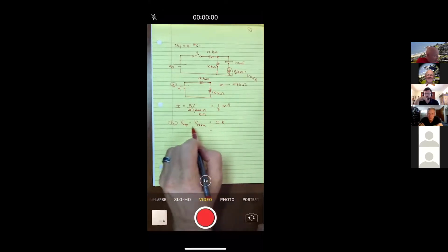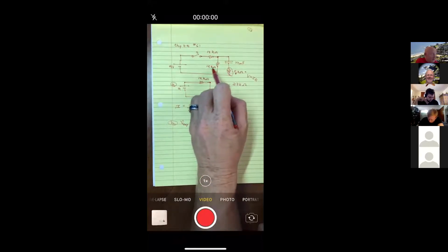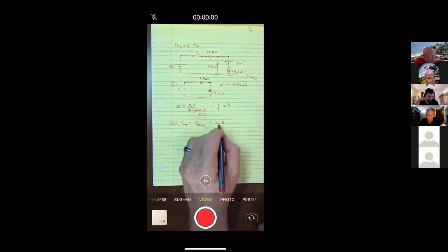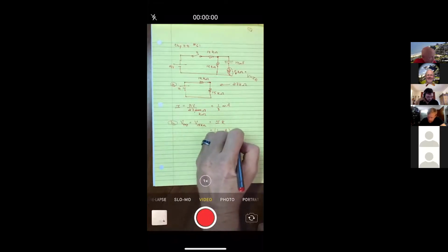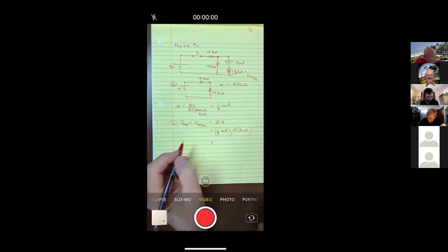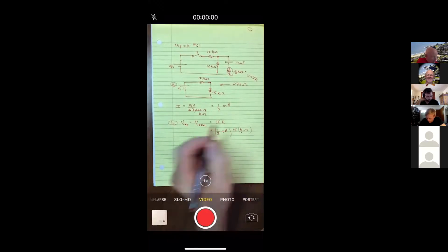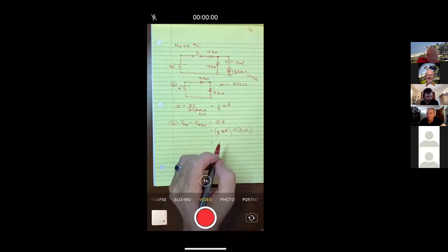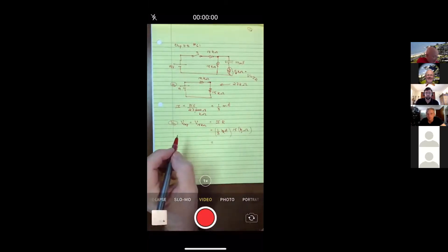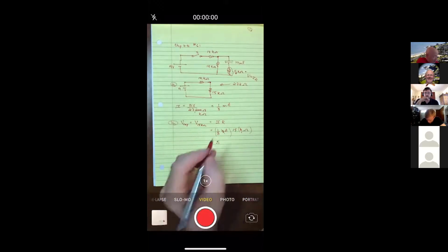So I'm going to be able to figure out what the voltage is on the capacitor by realizing that it's the same as the voltage on this 15 kilo ohm resistor. So the current we just did a moment ago as 1/3 of a milliamp, and the resistance is 15 kilo ohms. And again, maybe another little mathematics here. A milli times a kilo would cancel, right? So this is 1,000ths and 1,000. And then 15 divided by 3 is 5. So 5 volts.